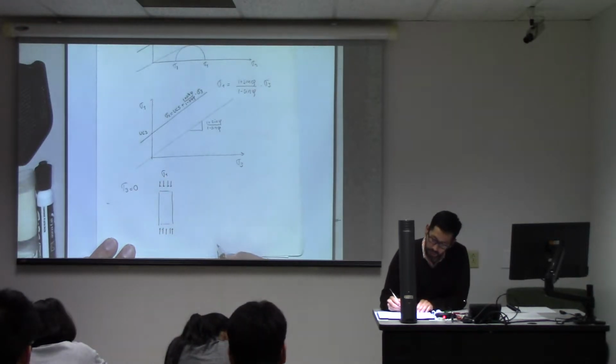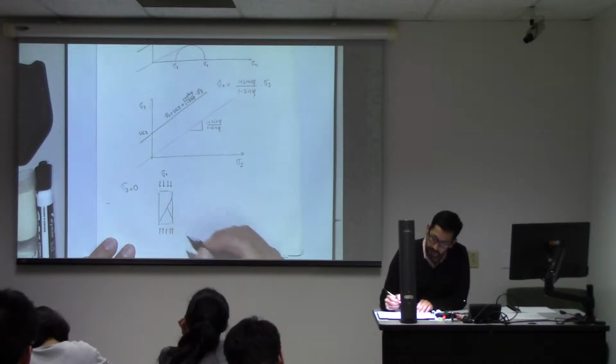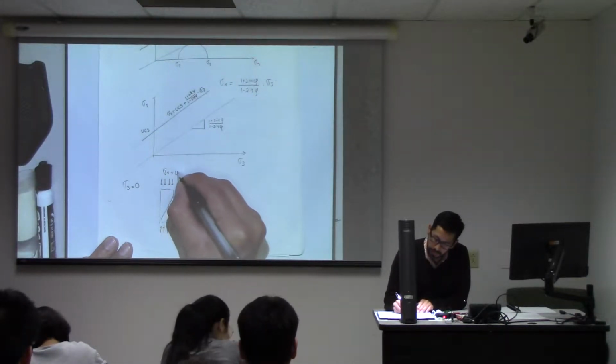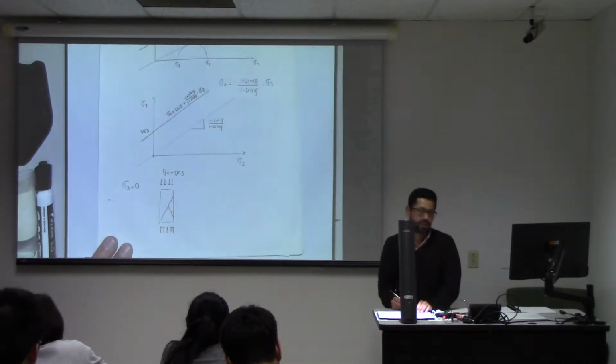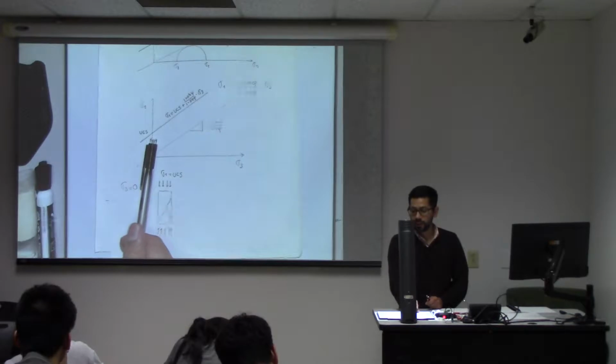This is sigma 1, and if you get it to failure, ideally shear failure, you're going to call this value unconfined compression strength, UCS. And this is that value over here.